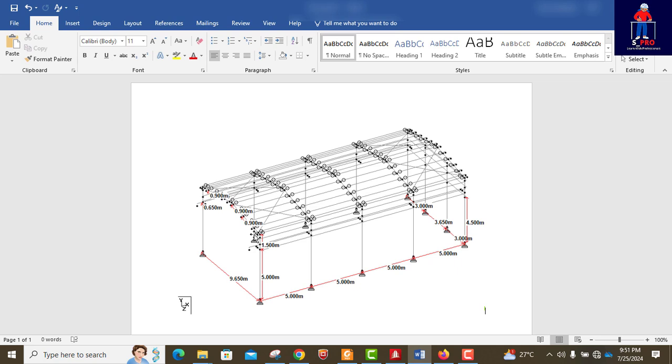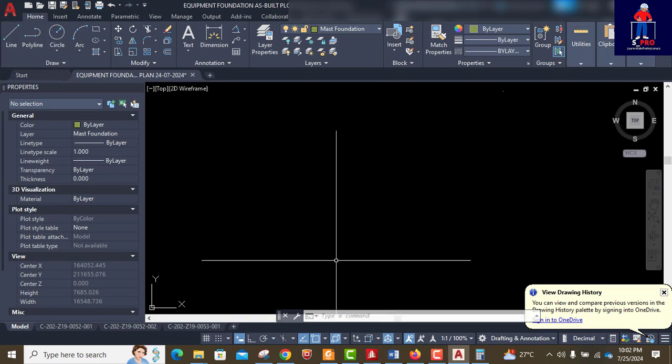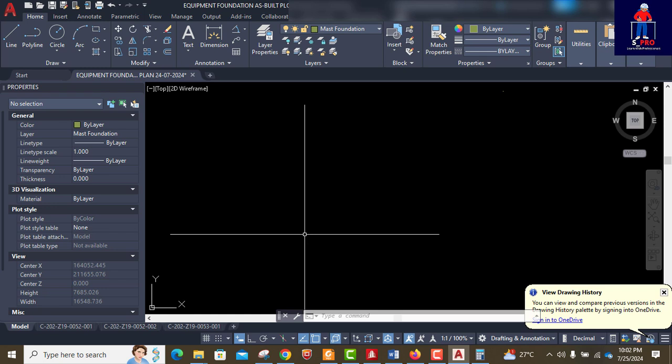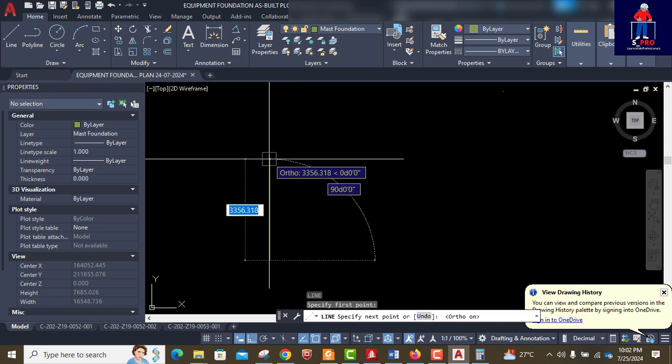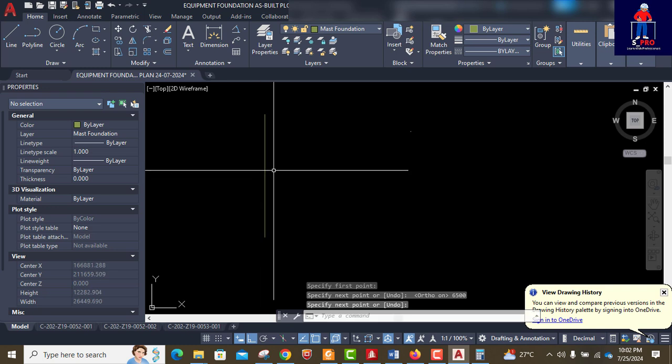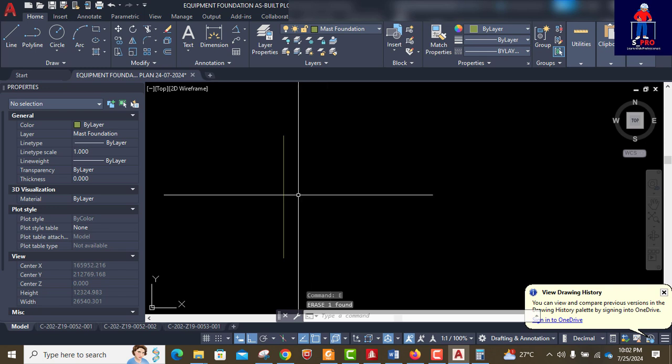We are going to use AutoCAD now to do a simple drafting to be able to establish our angle of inclination of the rafter before we come here to implement that. Okay, so let's demonstrate that quickly. I will simply draw the columns. For each of the columns we have 5 meters plus 1.5, that is 6,500. Okay, so this is the complete height of one column.